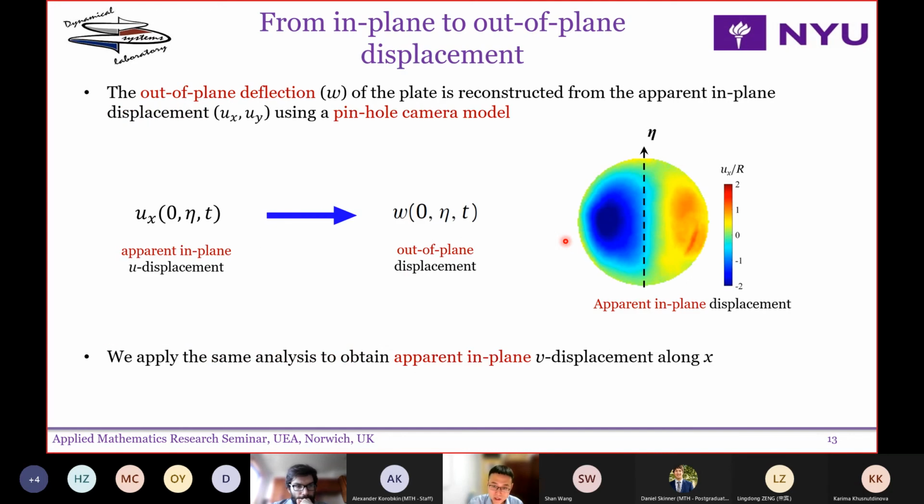And for the structural deformation, I mentioned before that there is an extra step that we took to convert the in-plane displacement that is measured directly by DIC into the out-of-plane displacement. The idea is actually very simple. We used the perspective of the camera. When an object moves closer to the camera, the object appears bigger. So similarly, if you consider two speckles on the panel, their distance appears bigger if they move out of plane towards the camera, right? That is just due to the perspective of the camera, and we can use that to establish a relationship between the in-plane measured displacement and the out-of-plane displacement.